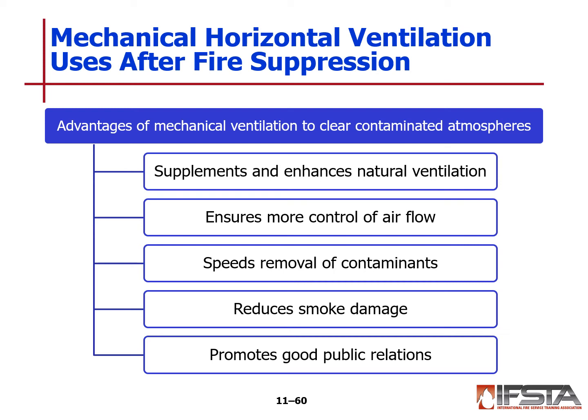Advantages of mechanical ventilation to clear contaminated atmospheres. This supplements and enhances natural ventilation. It ensures there's more control of the airflow itself, and it speeds the removal of contaminants. Reduces smoke damage if we coordinate and open doors and close doors correctly, and it promotes good public relations.